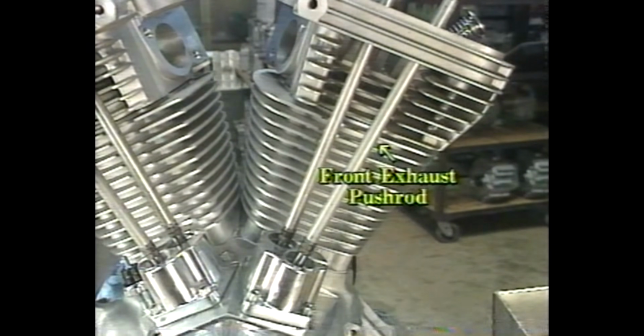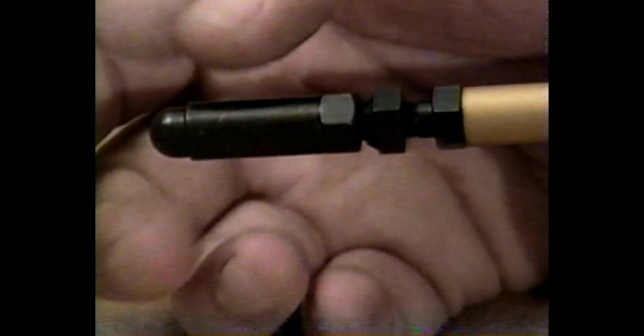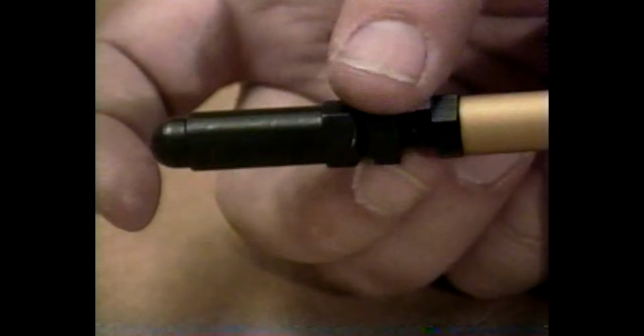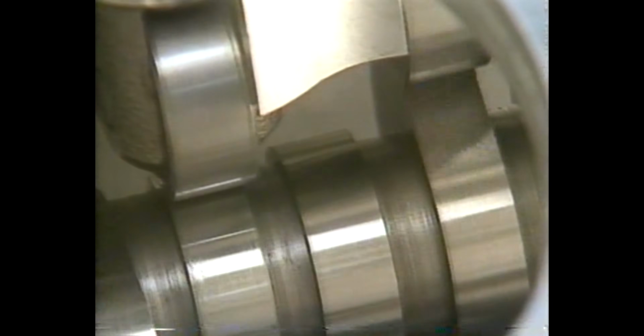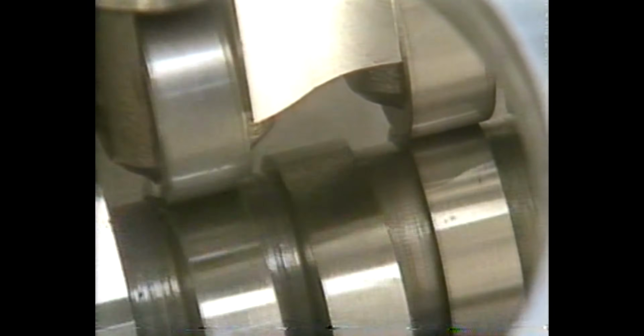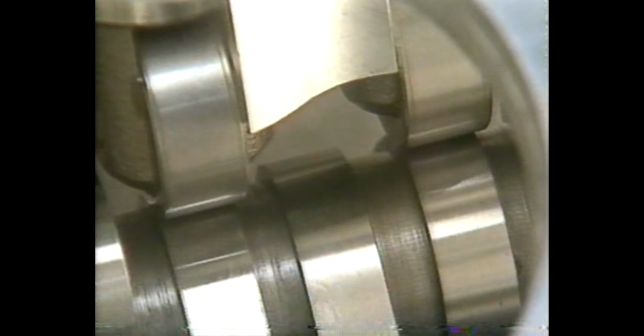As a general rule of thumb, we limit the use of adjustable aluminum push rods in Evolution engines to camshafts with valve lifts less than 550 thousandths of an inch. Cams that have valve lifts over 550 thousandths cause aluminum push rods to flex and fail under the extra valve spring pressures and stresses of this design.